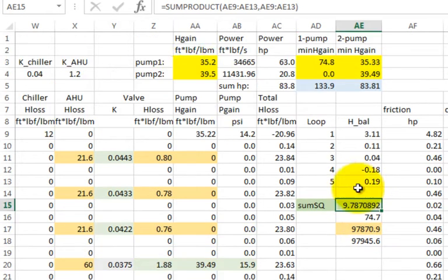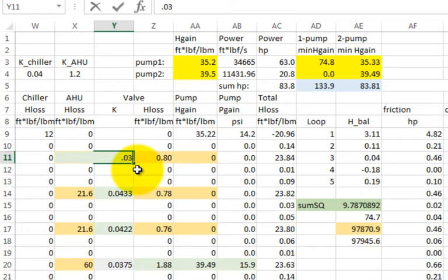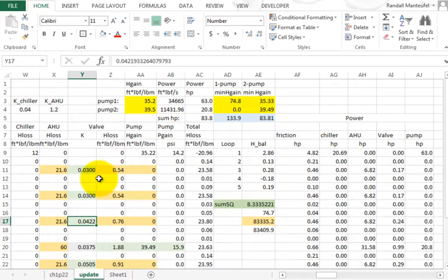So let's say that I didn't know what the head was, nor the valve settings. I could start these at 0.03. Well, that's actually too low. It's got to be 0.0375 or greater, so 0.04. Oops, 0.04. Let's come back down here. Leave that one alone. This one, fine. I'll just leave those two partially closed a little bit.